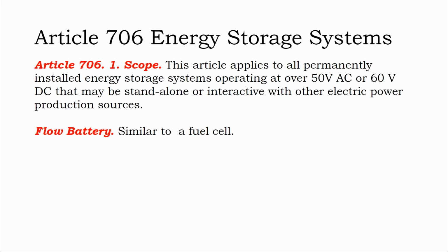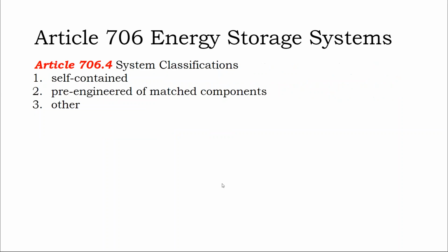Higher voltage is cheaper than higher amperage. So we're going to be moving away from the 48 volt kind of home backup power standard and into higher voltage battery banks. And this is the section that governs that.